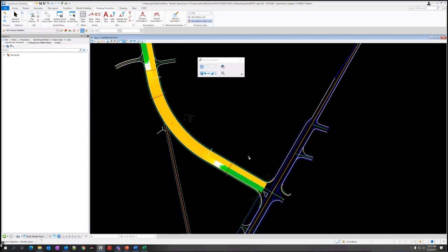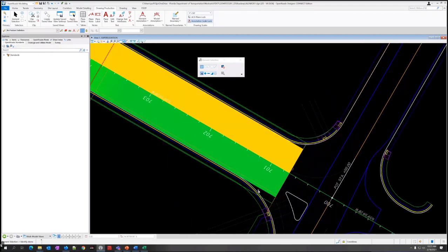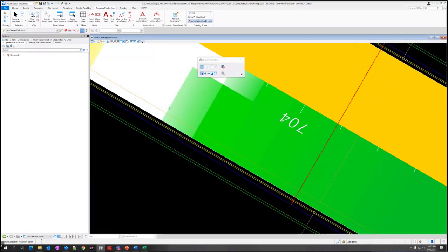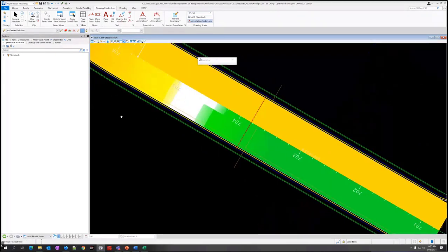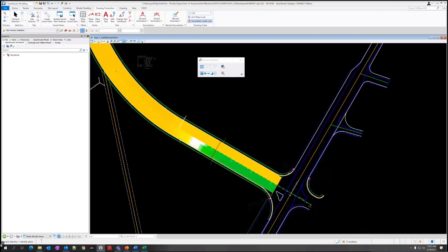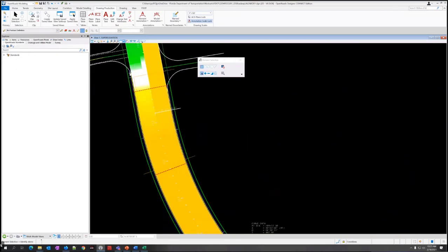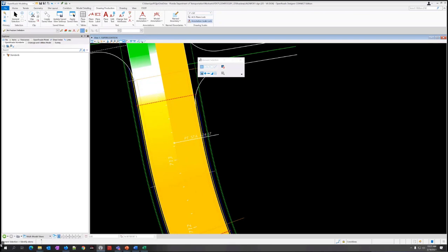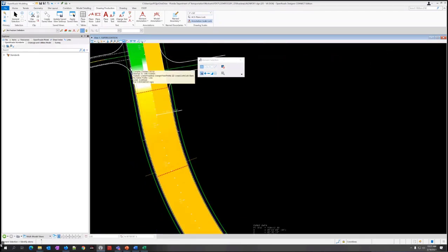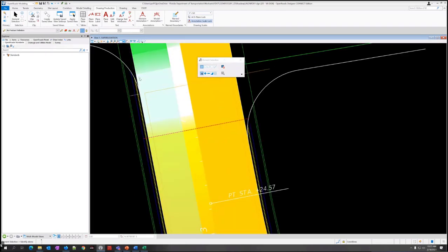Now, we actually need, so there's different ways to do it, so on the outside of the lane, this curb needs to match this super elevation section. Now, there's different ways to do it. You can certainly just do a point control manually and say, from this station to this station. But we could also do a super elevation lane and basically super elevate that curb. It's a little bit, there's a few extra steps with that because of the way we split it. So it's in a different model.